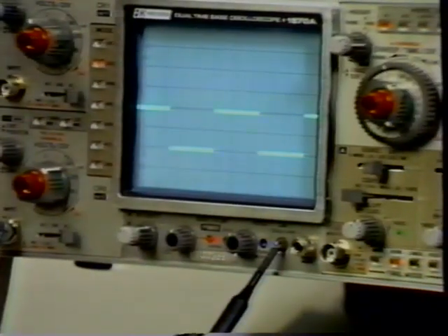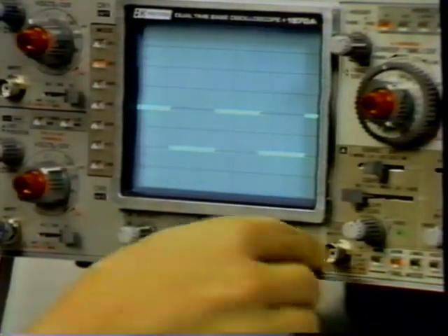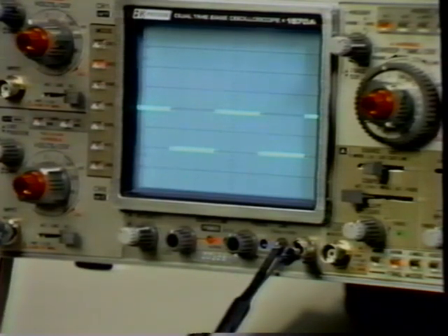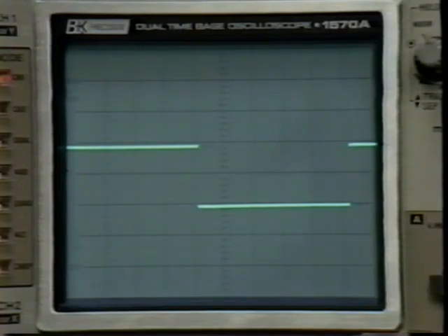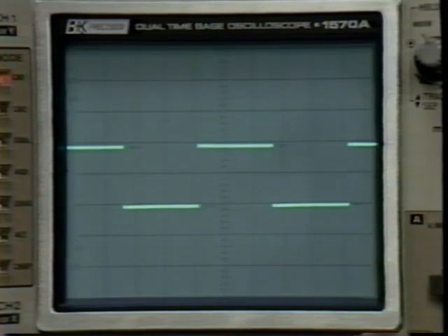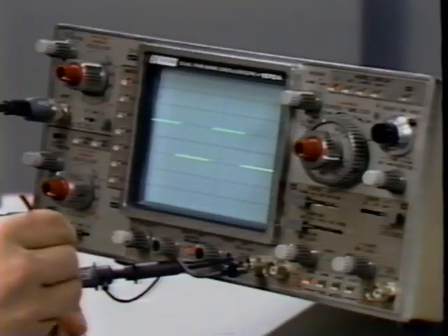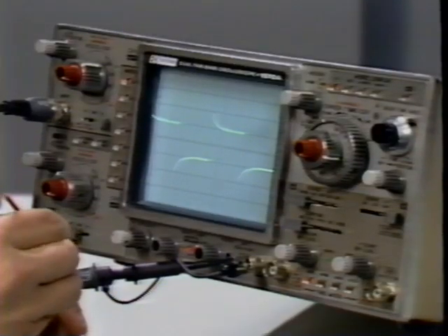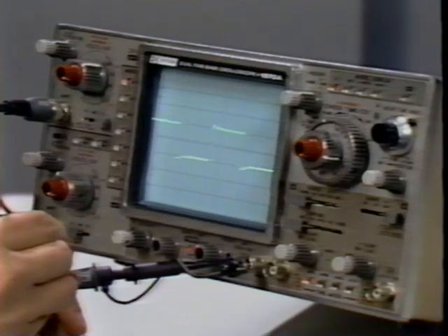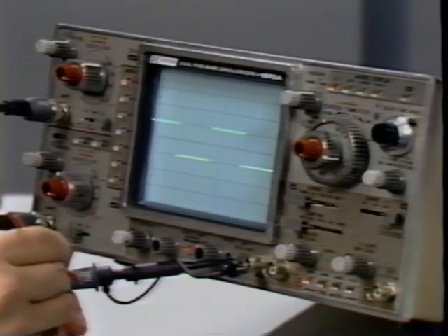Set the probe to the ×10 setting and connect it to the Probe Adjust tap on the front of your scope. Ground the probe to the scope's external ground tap. The calibration waveform displayed will normally have a frequency of 1 kHz and an amplitude of about 1 volt peak to peak. Set your scope to display several cycles of this waveform. Adjust the probe's trim cap so that the wave is perfectly square with no rounding, spiking, or ringing.